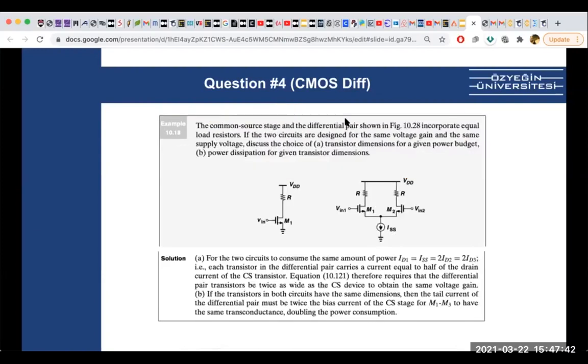Yeah, well, we were comparing these two circuits, right? So this is a good maybe exam question. So there is this differential amplifier and there is this common source amplifier. And when we look at the AC, we were cutting this and everything is ground. So this is ground, right? So we can simply look at this circuit in the AC domain. This is called half circuits, which I will explain in the next slides. But just to analyze this circuit, we can look at this circuit in the AC domain. And of course, in the DC domain, we also need to find GM.